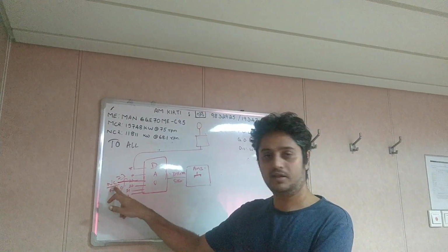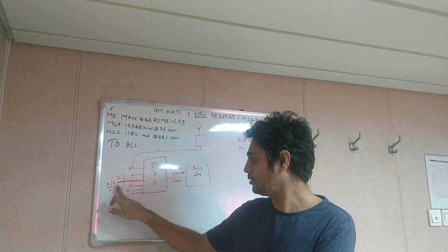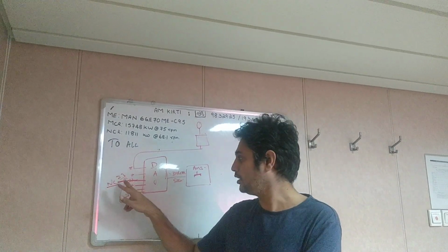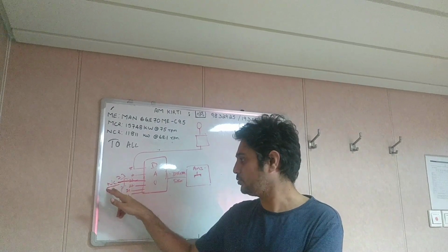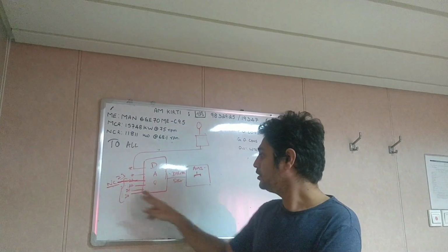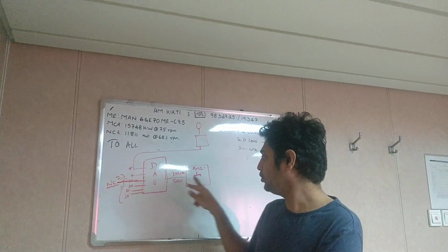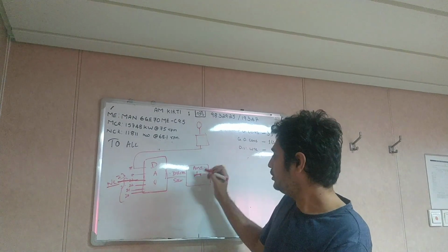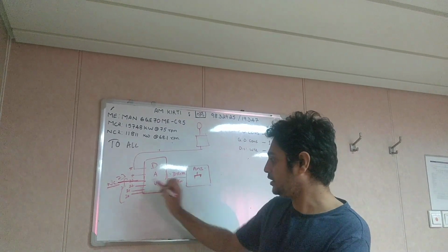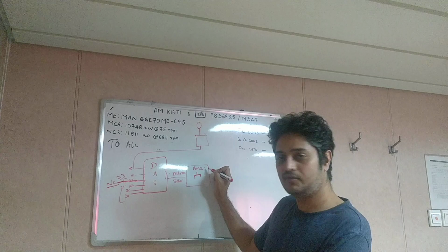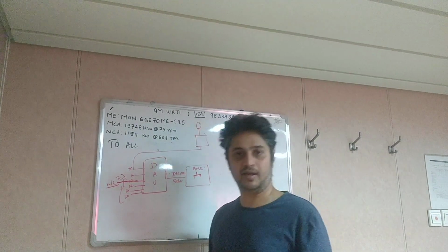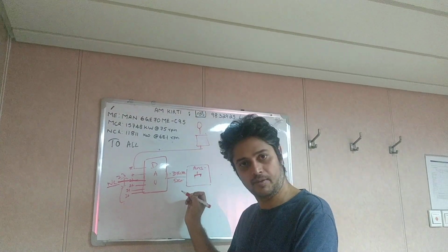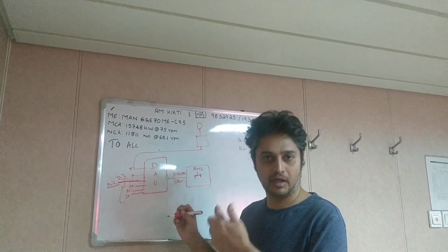So this is normally NC. Suppose this is normally NC as per the circuit, you can see in the circuit drawing, in the channel number. If it is put NC, it means that when it becomes NO, only then the alarm will come. Here you will have an option in the AMS. You need an alarm. If you select this channel, 23, you have to first select the alarm and then go to alarm tags. Then you will see all these things, from which channel number the alarm is coming.